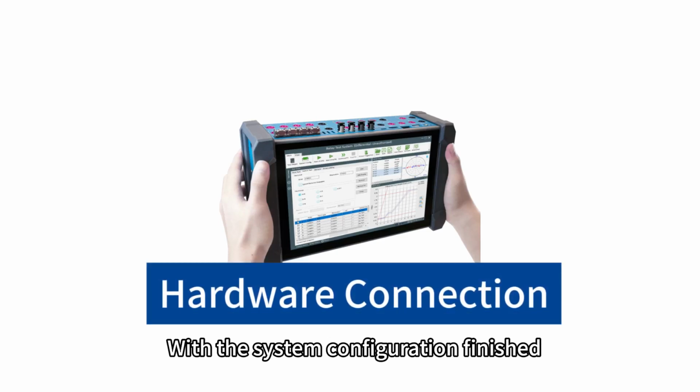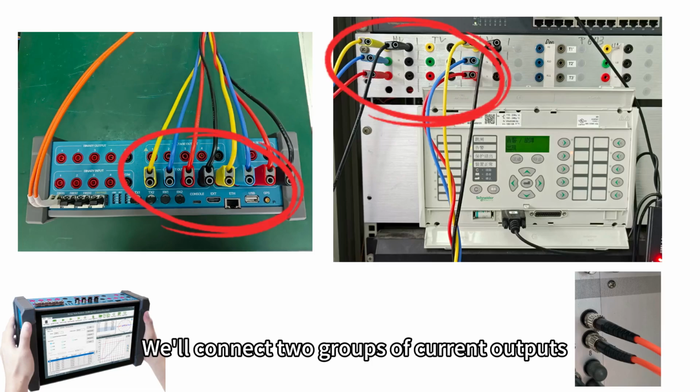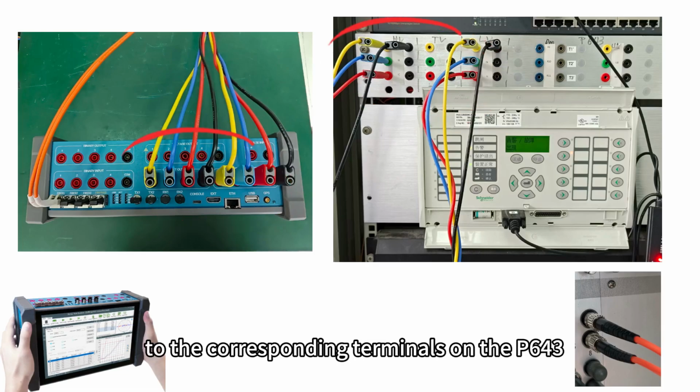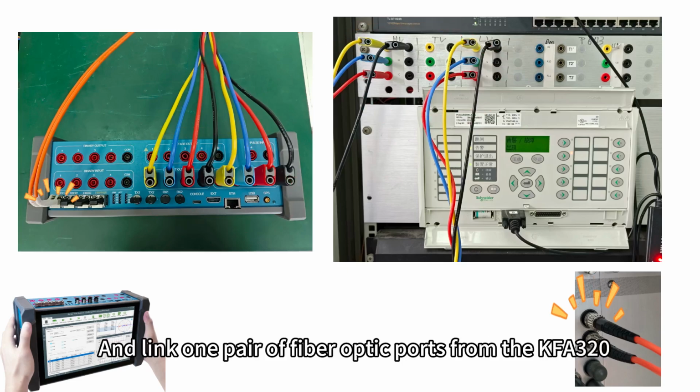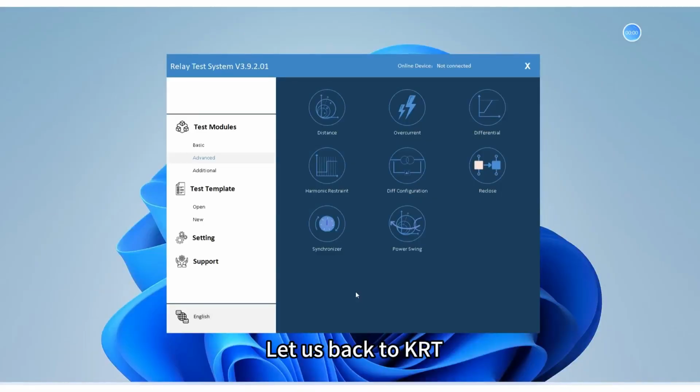With the system configuration finished, let's move on to checking the hardware wiring. We'll connect two groups of current outputs from the KFA320 to the corresponding terminals on the P643, and link one pair of fiber optic ports from the KFA320 to the relay to establish GOOSE communication. Let us go back to KRT.